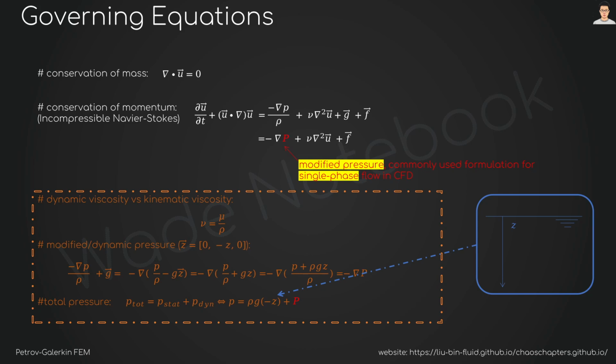On the other hand, if we want to study the fluid dynamics of multi-phase flow or free surface effect, like ocean wave or stratified flow, it is a good idea to include the gravitational term explicitly in the Navier-Stokes equation and the associated finite element formulation. In other words, the decision is made case by case.